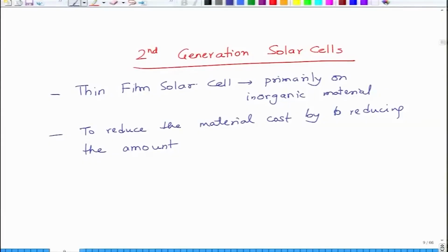You could make cleaner materials in thin film form. In thin film form, the cleanliness is very important, because if a small dust particle gets in which is of the same dimension as the thin film, your thin film will be dead. So that is why you require a very clean atmosphere for thin films, and that is why vacuum is preferred over air.